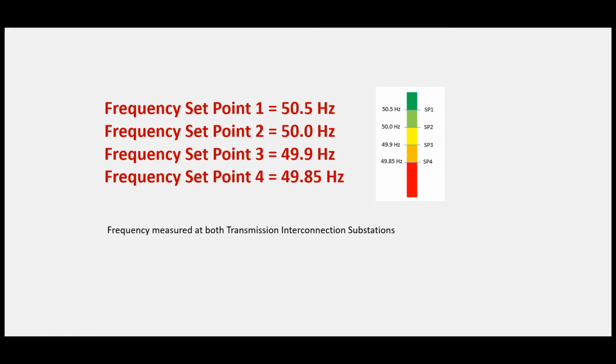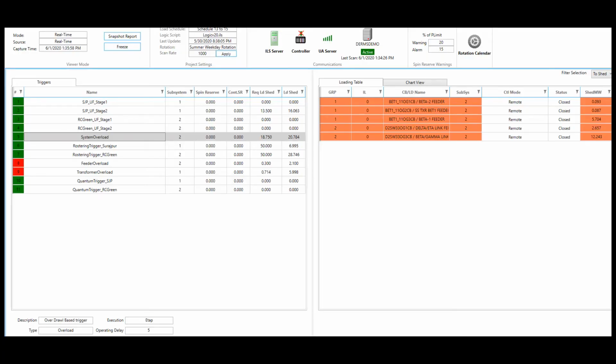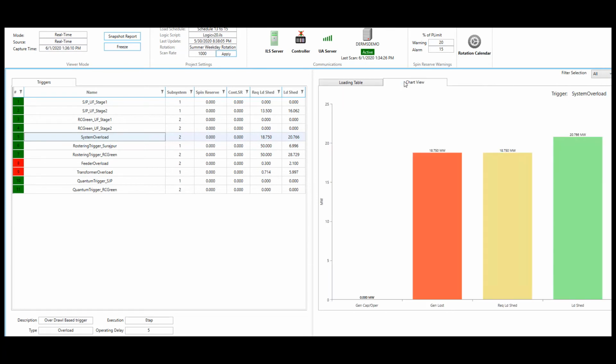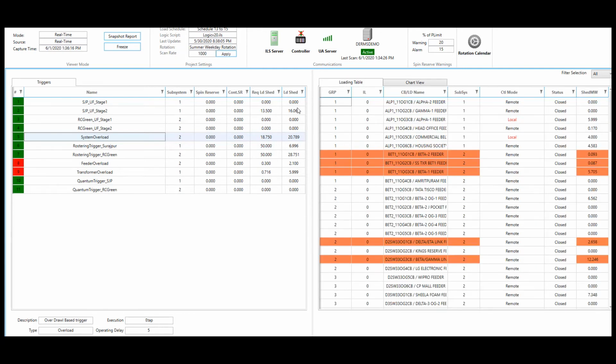The ETAP distribution load sharing system can intelligently monitor these parameters and make decisions to reduce penalties faced by the utility, as well as minimize the number of loads that get shed, thus effectively increasing the quality of the system. In this demonstration, the two transmission substations are not synchronized with each other, and thus the entire distribution network effectively operates in a split configuration.